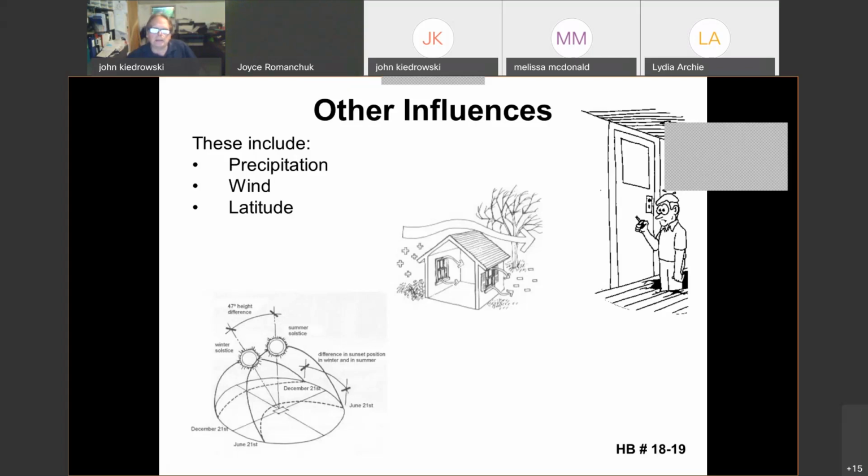How does the wind impact our environment as far as where you're located, which gets us down to latitude, and also we start looking at the orientation to the south, ideally to gain heat, and reducing the amount of openings on the north to reduce the cold influence of heat loss on the north side. But let's face it, in the ideal world, not every house is built to a north-south orientation.